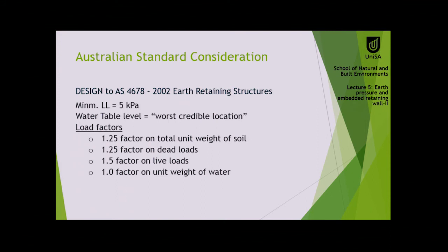The water table in the retaining wall: if the retaining wall is a gravity wall or cantilever type gravity retaining wall we learned last semester, if they are in a bridge approach in roads, that may be okay, because we make sure those are drained.